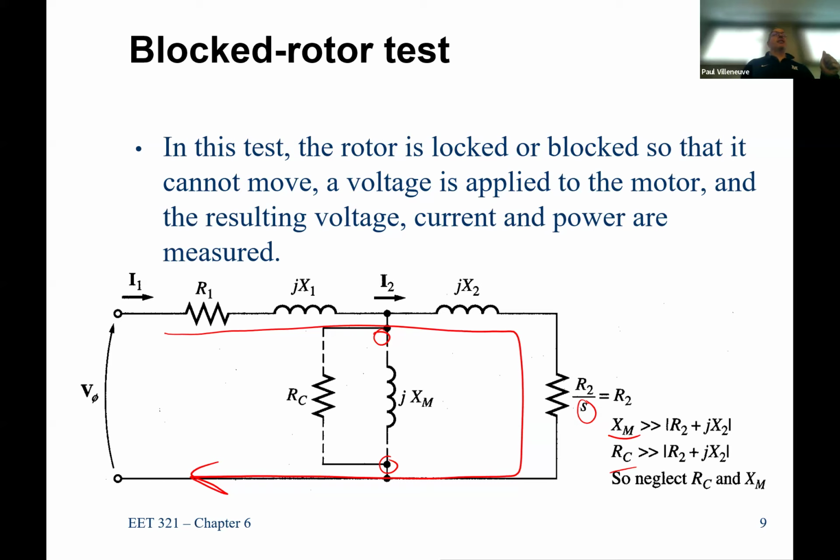Magnitude and frequency. The whole thing about an induction machine is the higher the difference in speed between the synchronous speed of the machine and the actual operating speed, the bigger the voltage and current generated on the rotor circuit. So how do you make that smaller? You run it at a lower frequency.